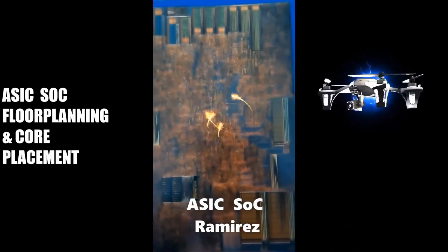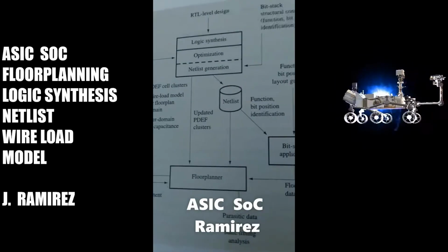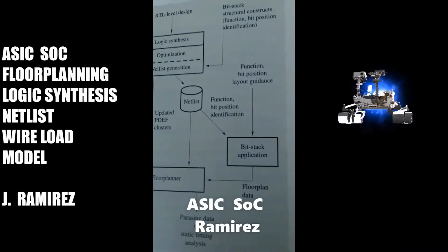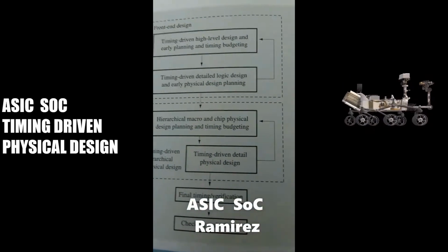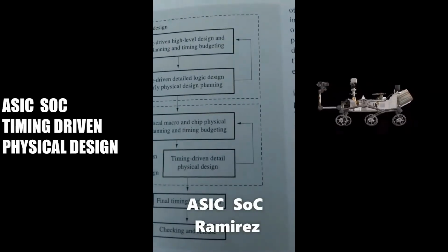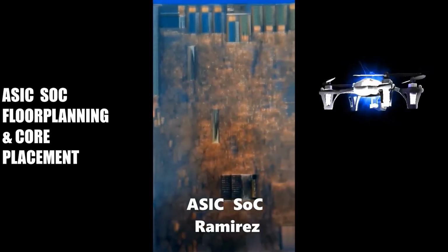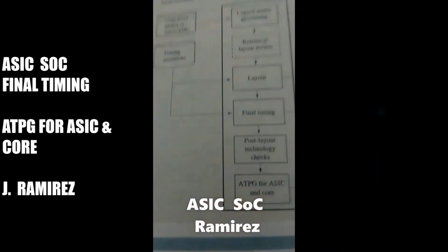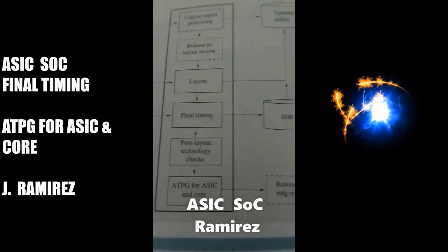The design of a bit stack uses a general methodology. First, data flow logic is logically separated from control logic. Then each data flow bit position, typically spanning numerous data flow functions, is isolated and its circuits are placed along the same circuit row, minimizing the amount of wire required for the buses.